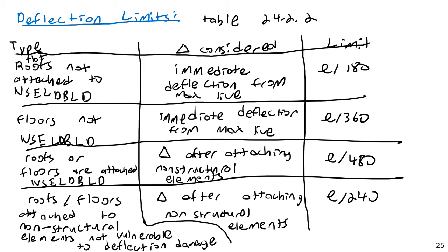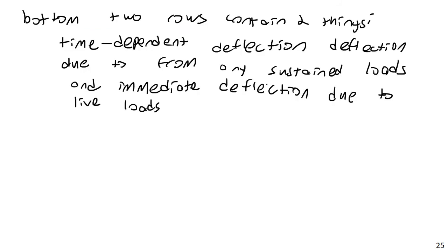So if you look at equation 24.2.4.1 that we discussed previously, the verbiage actually meshes nicely here. It says, unless obtained from more comprehensive analysis, additional time-dependent deflection resulting from creep and shrinkage of flexural members shall be calculated as this. So basically, you use your lambda here, multiply it by the initial deflection, and you compare it to that there, plus adding any live load. So again, let me summarize this.